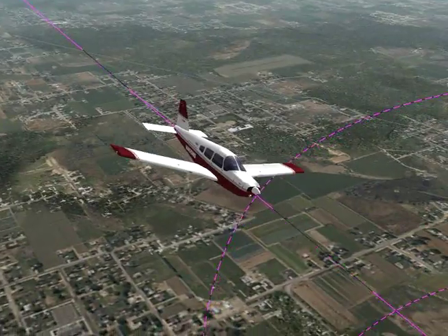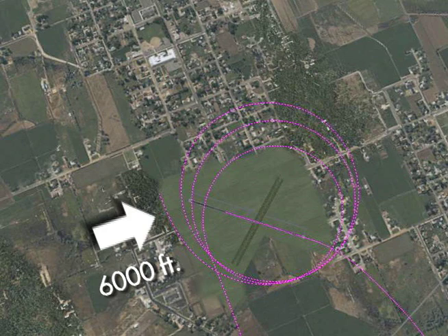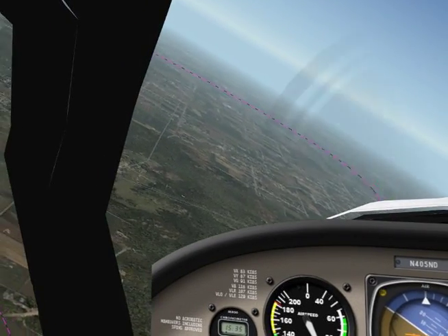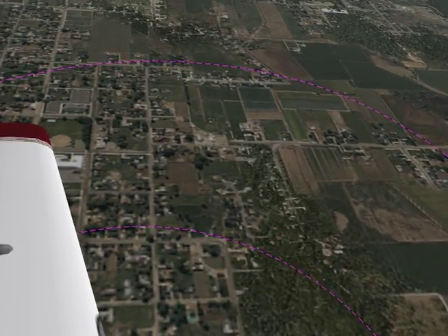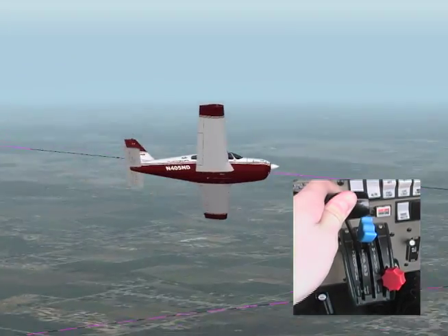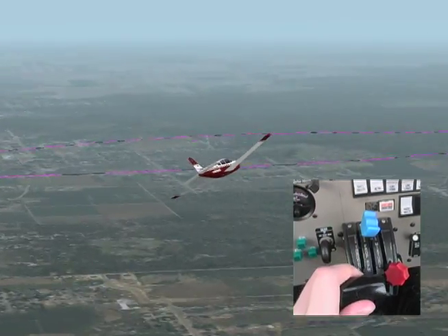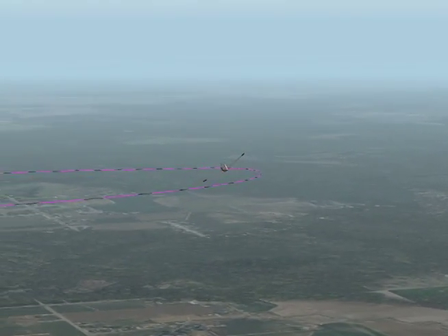Keep in mind, unlike turns around a point, as the aircraft descends vertically, wind direction may and usually does change. Therefore, the pilot will have to constantly adjust control inputs to compensate for changing wind conditions. Also, the pilot should perform what is known as clearing the engine, where at the completion of each turn, power is brought forward smoothly and then reduced back to idle in order to avoid fouling the engine's spark plugs and to aid in creating residual heat for the engine during cold weather operations.